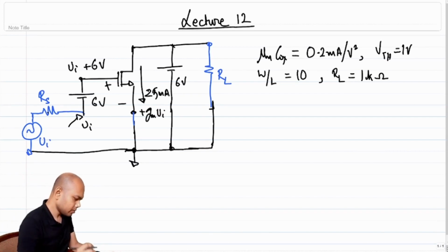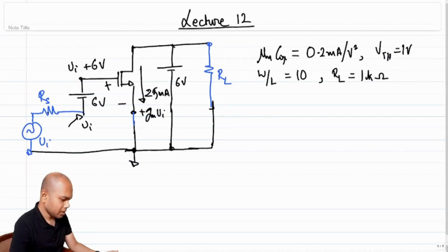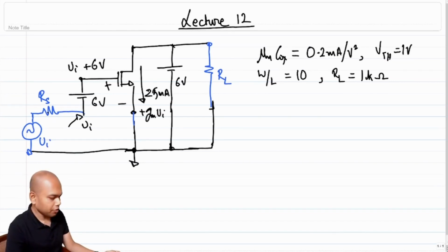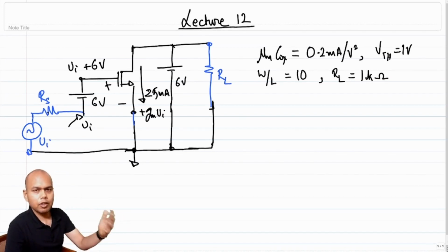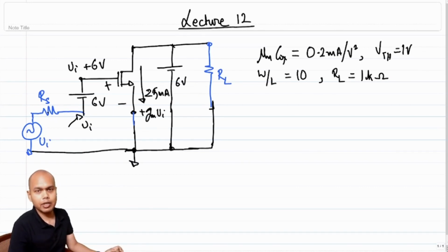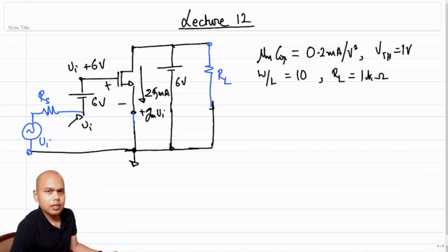In the previous lecture, we were trying to build an amplifier which was supposed to give us some amplification of power using a MOSFET. We noticed that in order to arrive from the small signal incremental model of our MOSFET to a full-blown MOSFET architecture with all the biases in place, we had to make some adjustments in order to accommodate the required quiescent conditions.